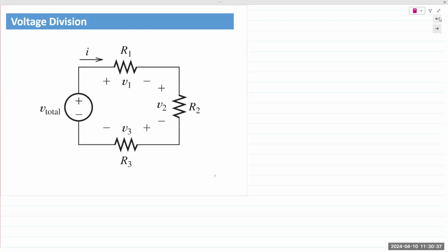What kind of circuit is this? Series or parallel? What happens to current in a series circuit? It remains the same, because the current that appears in a series circuit is a combined effort of all the resistors that are working together. It's quite evident because there is only one path for the current to flow through. There's no other path. So current is the same for all of them. What happens to voltage? It's right there in the word.